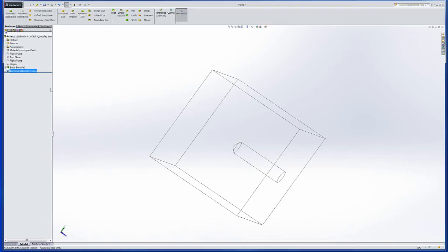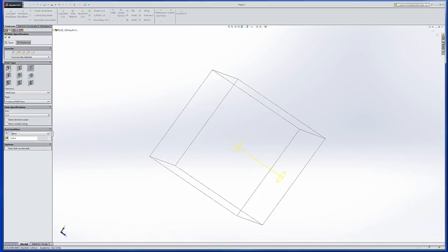So now we'll look at changing that up a little bit. We said we could edit that and make changes to that hole. Well, let's say we wanted to make that a counterbore hole. To do that, we can go in there and see that down at the bottom, I'm going to turn off the countersink. But on the sizing, show custom sizing. And here are my different options.